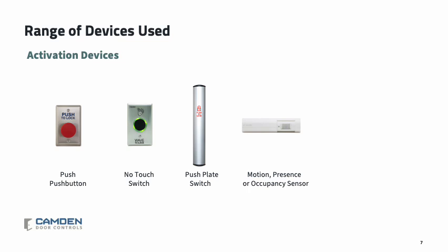Rather than using a switch to lock the door, it is possible to use a sensor to detect when a room is occupied. There are a wide variety of detectors available, but it is essential to match the sensor operation and the beam pattern of the sensor to the physical design of the room where it is being installed. This is to prevent false activations.